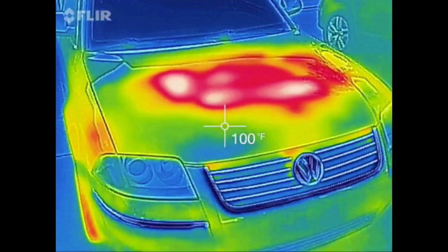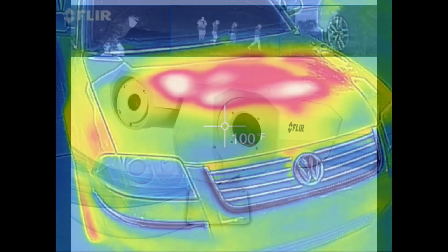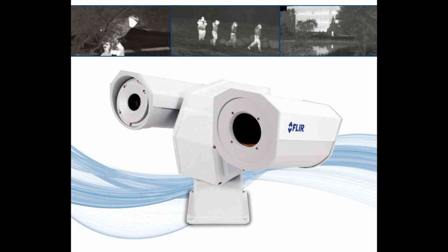If there is a reference heat source in the field of view, with a known temperature of radiation, it is possible to calibrate such temperature so that the object that you see can give you a relatively accurate representation of such object temperature. Of course, like with visible spectrum cameras, the size of the pixels, quality of the optics, and the processing electronics will define the precision of such measured temperatures. One should consider also the atmospheric conditions between the object and the thermal camera, such as smog, fog, dust, rain, or snow.